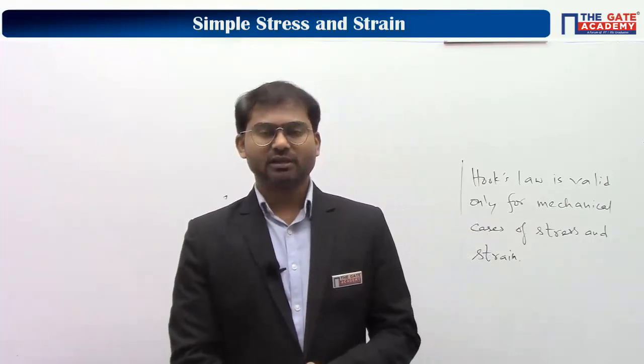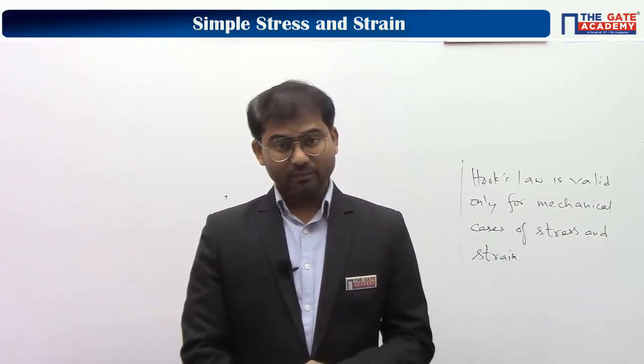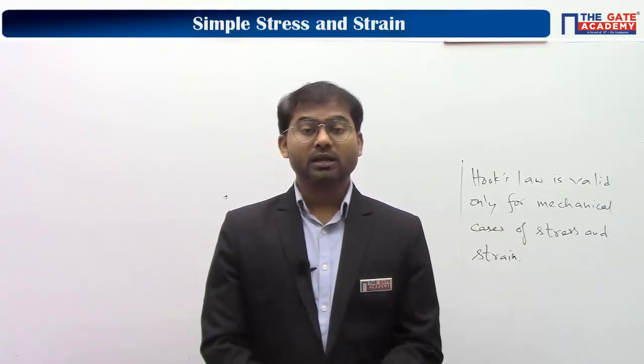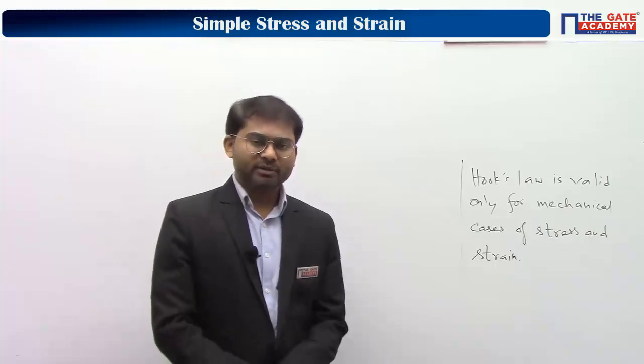In the same way, using engineering stress and engineering strain, you can again calculate true stress and true strain. Also, after drawing the conventional stress-strain graph, you can calculate the value of Young's modulus, because that is the slope of the curve up to the proportional limit, which we're going to study a little later. So Poisson's ratio, Young's modulus, true stress, true strain, engineering stress, engineering strain, all are calculated values. The measured values are only load and elongation. Kindly remember this.